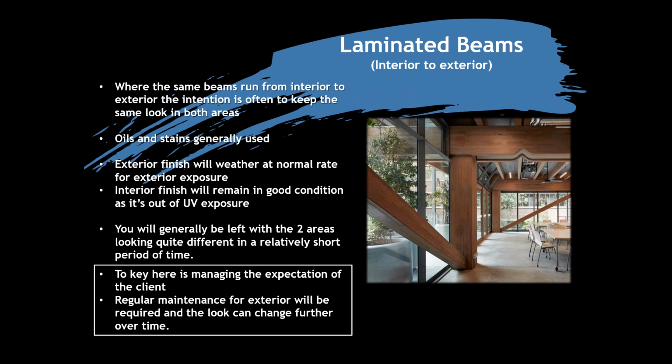here in New Zealand. So I saw one the other day where interior was looking magnificent with an oil stain on it, and the exterior 3 months later had pretty much weathered off in our conditions. So it's a really tricky thing to keep that same look flowing from interior to exterior, even with other stains that we'll talk about in the next few slides, because quite simply that exterior environment or exterior situation is going to weather very quickly, your interior is not.